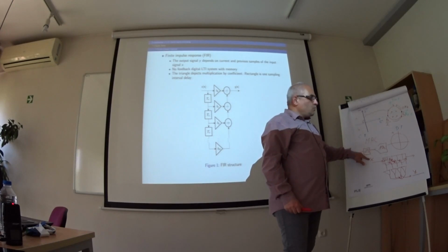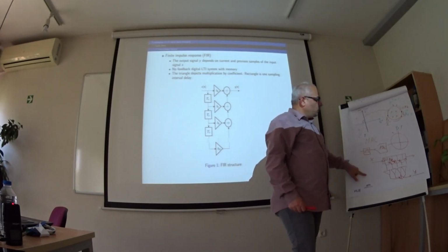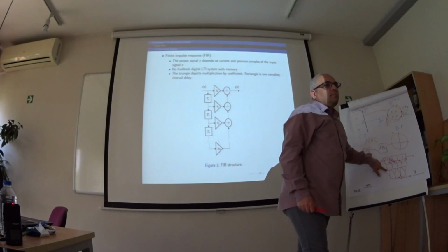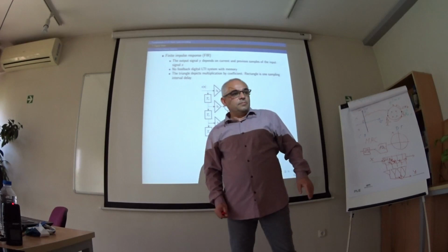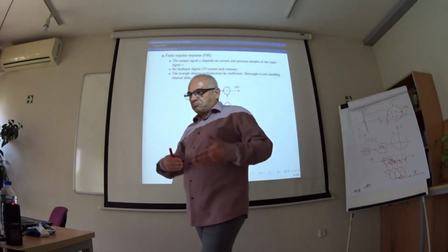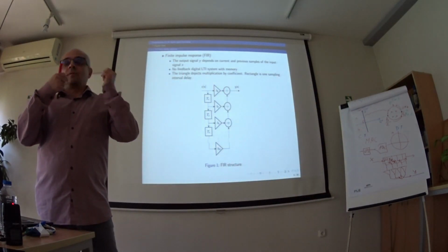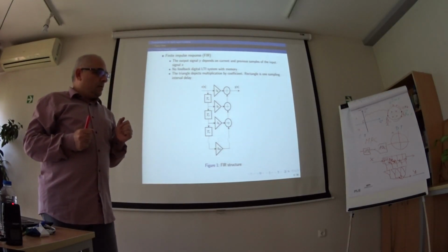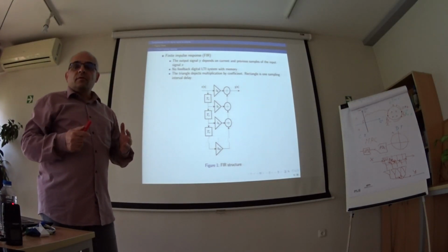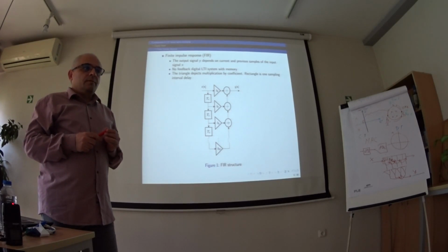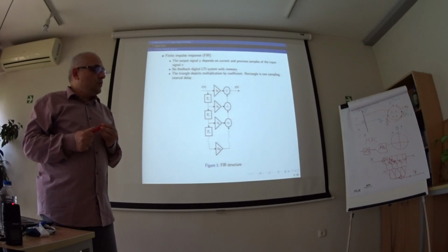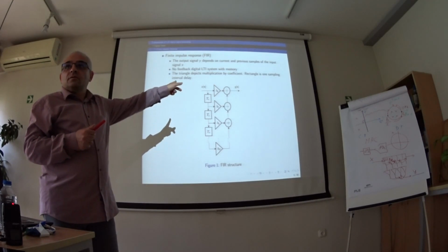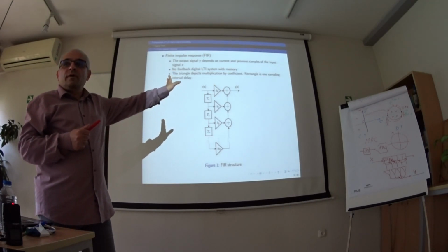We want each harmonic, each spectral component to be delayed by an identical amount of delay, because we want to sum them at the output with the right phase. We want the same delay, and to achieve this we want linear phase response, which can be achieved only by FIR, not in analog domain.